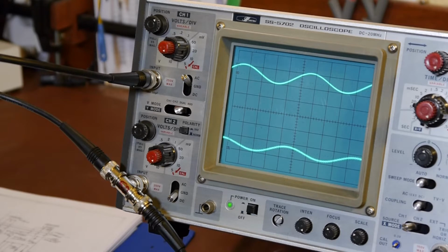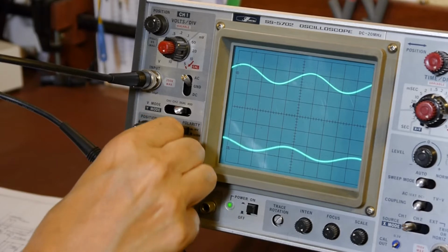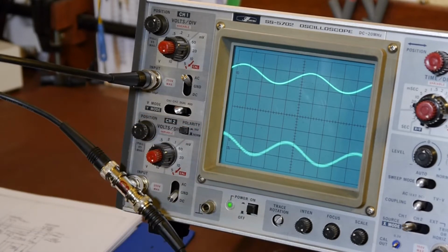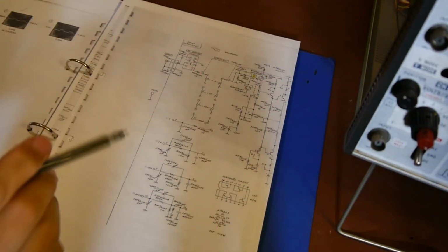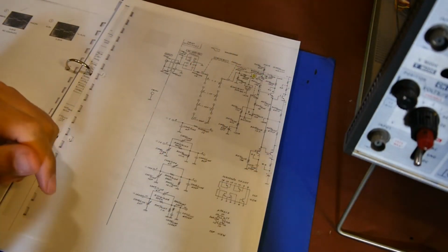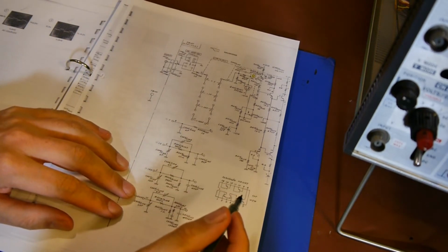So I think what we need to do is have a look at the switching circuit now and the makeup of the vertical attenuator section to find out, is there anything common to the 2, 1 and 0.5 volt inputs which would explain why we're getting a problem. Well, I'm hoping you'll be able to see this, but if not, I'll blow it up on the computer later, and so you can actually see it.